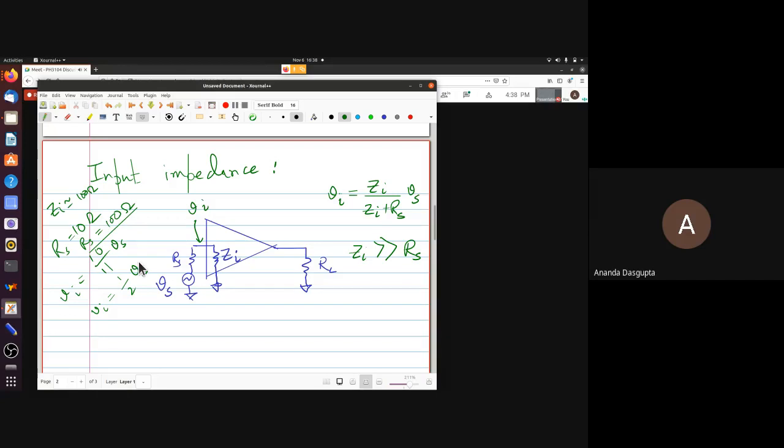Once again, it's the stability of the behavior of the circuit which is important. You want a large Zi simply because you want the circuit to be stable. Clear? That is the real point. You want large Zi, not so much because it's going to give you a bigger gain, but more because it will give you a gain which protects you from fluctuations because you're changing your source resistance.